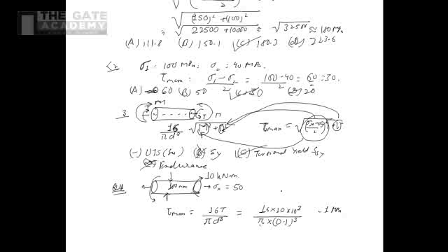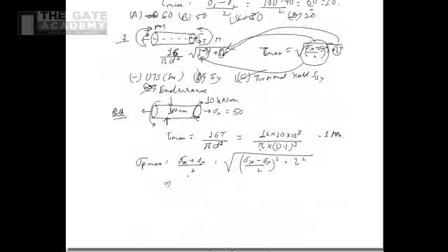Now the principal stress, so sigma P max is (sigma x plus sigma y) by 2 plus square root of ((sigma x minus sigma y) by 2) square plus tau square. Correct? Now we have no sigma y, only sigma x is there. So sigma x is 50 upon 2 because sigma y is 0, and again this is (50 upon 2) square plus 51 square. So this is 25 plus square root of 25 square plus 51 square.